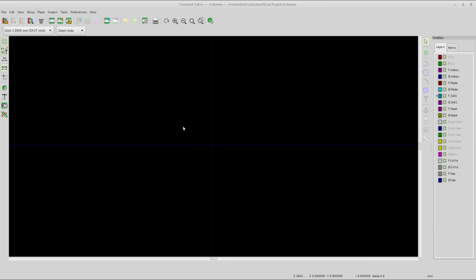And now you can start making the footprint. So then to actually start creating, you have a few buttons up here. This is going to be the one we're going to want. You could create one using a wizard, or you could load a footprint from a library. So this was kind of a thing I used to do every now and again, would be to load a footprint from some other library, and you basically like it, but you want to modify a couple things about it. You modify it, and then you save it in this current active library. Okay, well, we're going to go ahead, hit this one, and make our own new footprint.